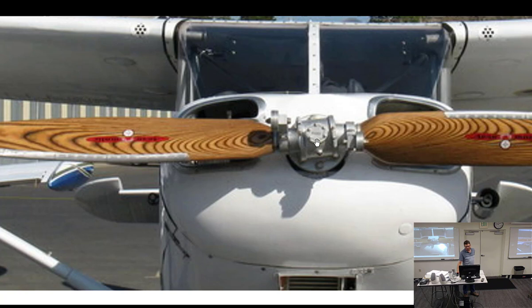What would happen is it would sense, at a high RPM, a loading that would indicate the way the air would hit. If you were in a climb, it would sense that climb and put it into a low pitch. Then if you were to level out, the way the aerodynamic loads would hit it, along with centrifugal twisting force and aerodynamic twisting force, mostly aerodynamic twisting force I think on this one, would cause it to go into a higher pitch.